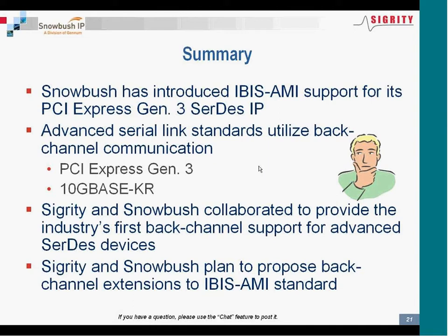And why is that important to simulate? It's important because it helps to accurately emulate the behavior of the hardware. Because as you saw in the real IP, the receiver is the decision point, and it's making decisions about the signal quality, and it's passing feedback to the transmitter in order to optimize its equalization settings. And obviously, how those settings get made has a huge impact on what the simulation results look like. And of course, you want that to emulate the hardware as close as possible so that you can predict what you're going to see in the lab.